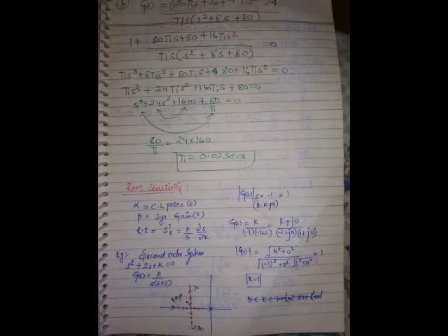The derivative term only is increasing the damping. Larger transient overshoot? Overshoot will decrease. Higher noise: why higher noise amplification? Because it is increasing bandwidth. Bandwidth increases means noise will get amplified.